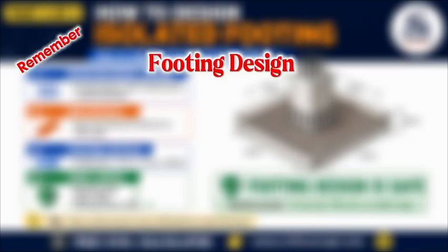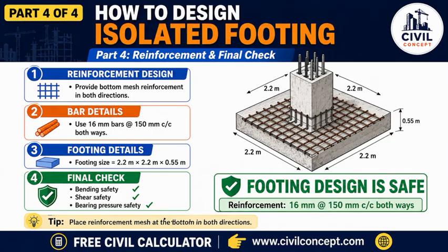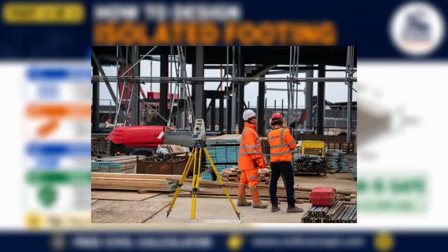Remember, footing design depends on load, soil bearing capacity, concrete grade, steel grade, column size and code requirements. So, actual site design must always be checked by a qualified structural engineer.